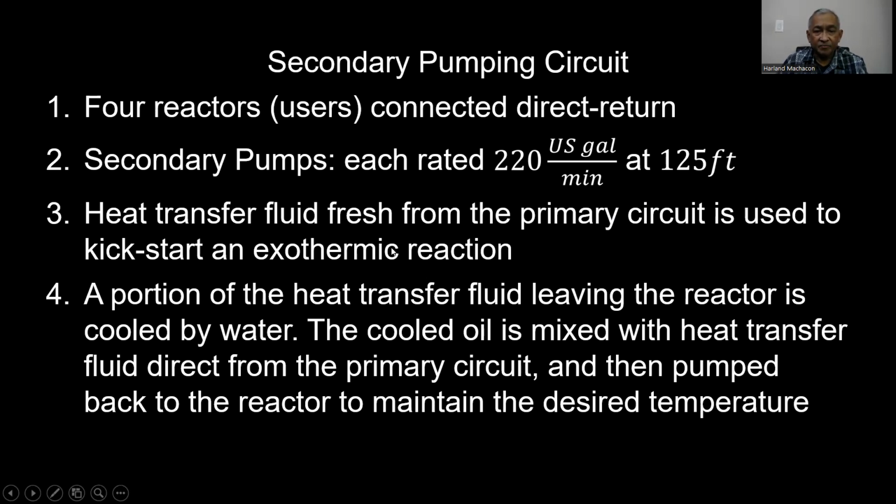Heat transfer fluid, fresh from the primary circuit, is used to kickstart an exothermic reaction during the heating mode. And during the cooling mode, a portion of the heat transfer fluid leaving the reactor is cooled by the water coming from the cooling tower, and this cooled oil is mixed with heat transfer fluid direct from the primary circuit and then pumped back to the reactor in order to maintain the desired temperature.